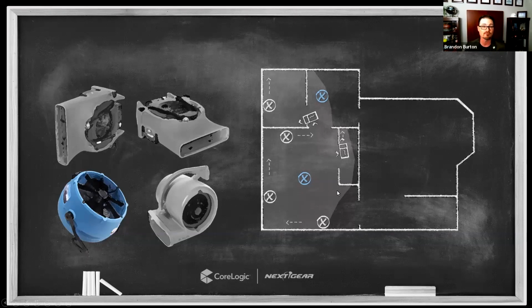And if there isn't sensible cooling, or if you want to get really precise, if there isn't the same temperature and humidity as you would get chest height down at the floor with a hygrometer, adjust air movement, install air movement, continue that process until we can validate that there is air moving across all wet affected surfaces. Okay. And this is key.